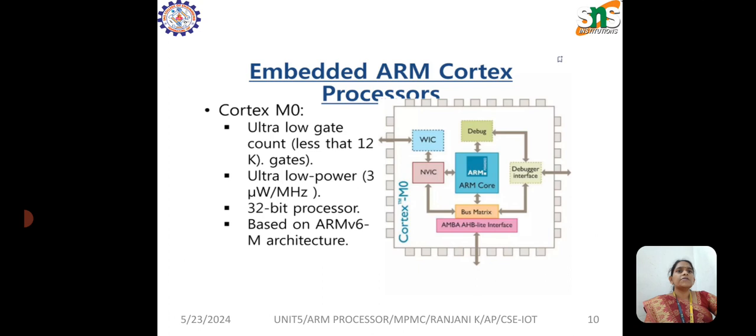Most ARM processors implement two instruction sets, a 32-bit instruction set and a 16-bit instruction set. The memory is addressed with a 32-bit address, and the data types can be 8-bit bytes, 16-bit half words or 32-bit words. It was the first commercialized processor, with a maximum of 25,000 transistors.